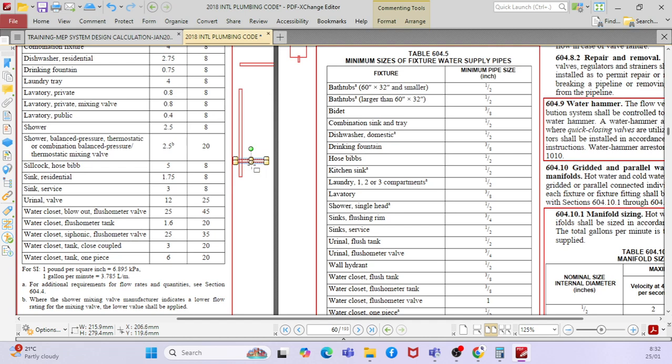You assume 20 mm. Say for example this is half inch, 15 mm, or 12.5 mm. So this will be 12.5 mm. So your pipe size as per the fixture is this type only, right? Fixture pipe only. We have to drop that one. Our header will be 1 inch, and for the fixture unit, if it is half-inch, then we have to provide a half-inch reducer.